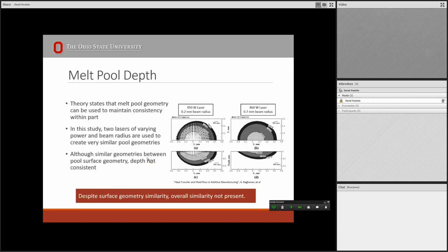I don't know if they mentioned this explicitly, but in the melt pool camera, there's a difficulty in reading the very highest temperatures because you saturate it. I don't know if they addressed that at all or not. Not really. They just mentioned that you could do this visually, looking at the melt pool, but they never really discussed how you would go about doing it. If you had just a high-speed camera, you really can't tell the difference in temperature. You can see this is open, this is not open. So maybe there's a thermal camera, maybe.